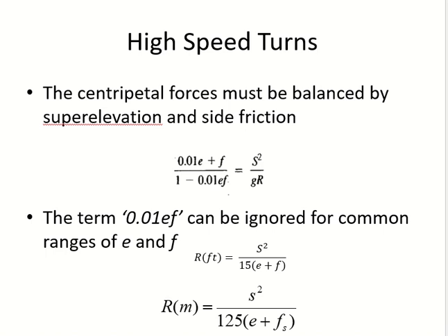For vehicles we have 4 important characteristics for the design of the highways. These characteristics include deceleration, acceleration, and turning, and the turning can be seen for low speed and for high speed. If you are considering a low speed turn, then the only thing we need to consider is the size of the vehicle, and the reason is the forces acting on the vehicle. There is less force acting on the vehicle when it is making a turn at a low speed, so if you just consider the space required according to the size of the vehicle, that's enough.